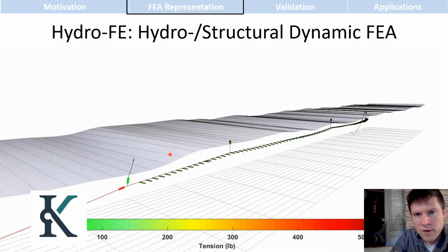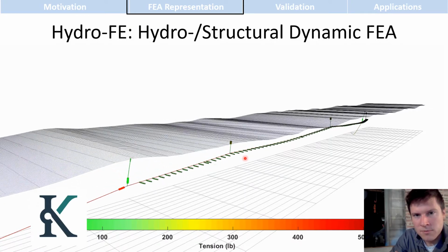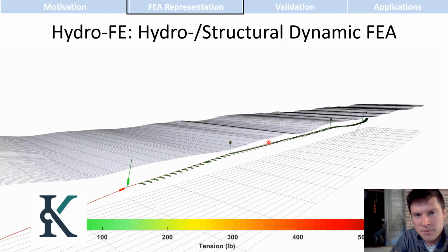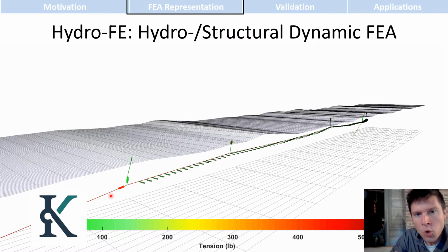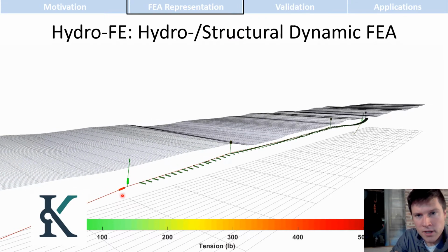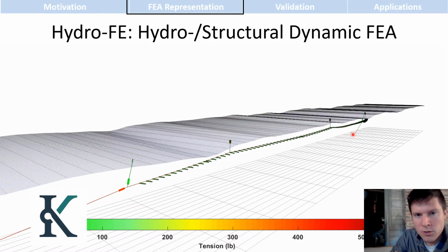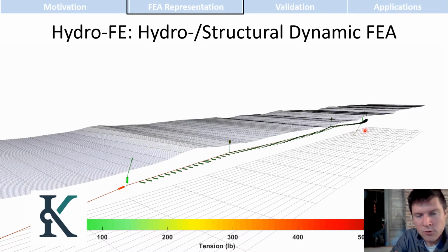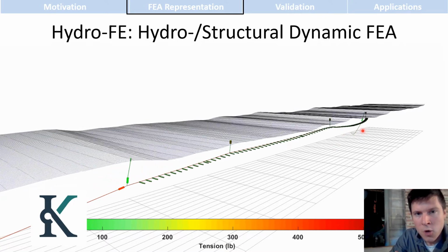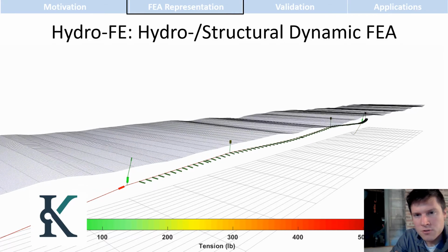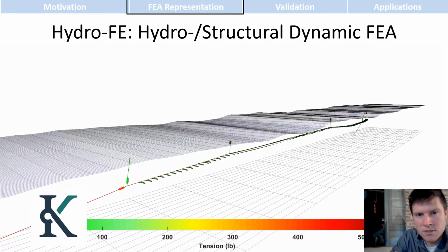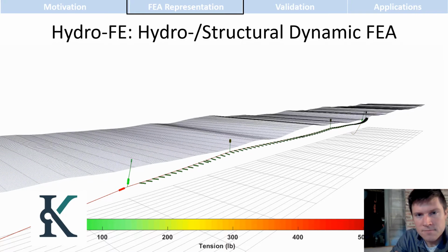We can then build finite element models of all kinds of farm designs and subject them to the maximum expected waves and currents for a particular site. We can predict things like maximum mooring line tension, or how far below the surface the kelp sags down when the farm deforms. We can also design for operational considerations, like how much force will it take to raise the line to the surface for harvesting.